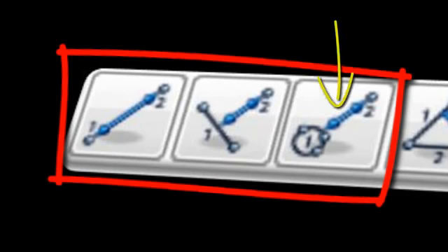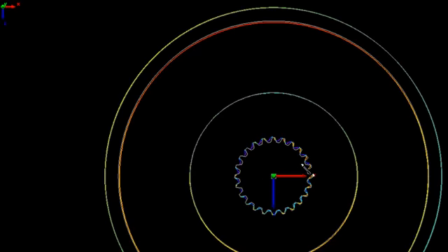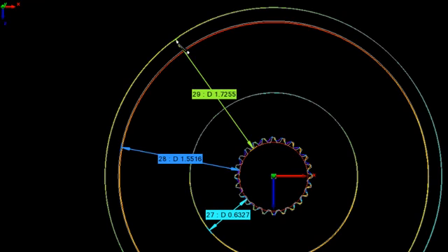Next, let's measure point-to-circle distances. Pick points to create your circle. A minimum of 3 points is required to best fit to a circle. Pick as many points as desired. Right-click when your circle is complete, and then pick points to measure the distance from the circle circumference to your point. Right-click to exit mode.